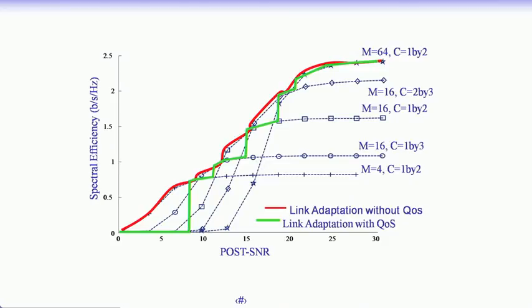Okay. So, at the end, if we look at the SNR axis and the spectral efficiency axis, what we see over here is that if we choose a fixed modulation code rate, as SNR increases, error probability decreases. So, spectral efficiency or throughput increases, and throughput saturates after a certain point, where there is no longer a notable decrease in the error probability.